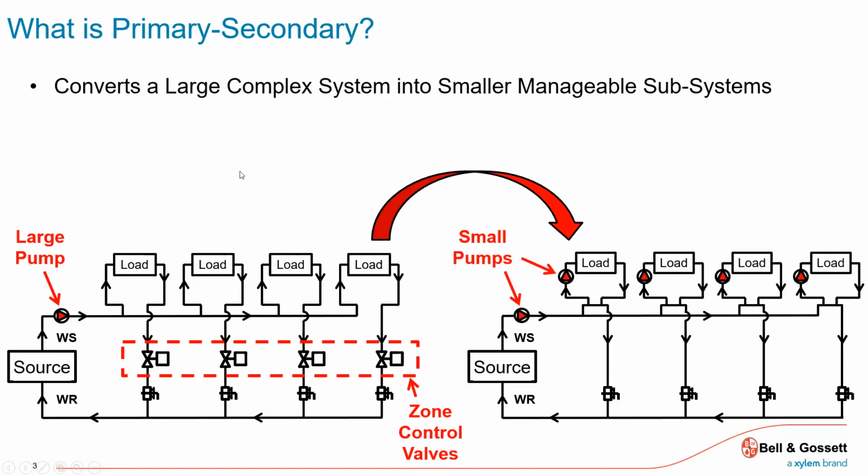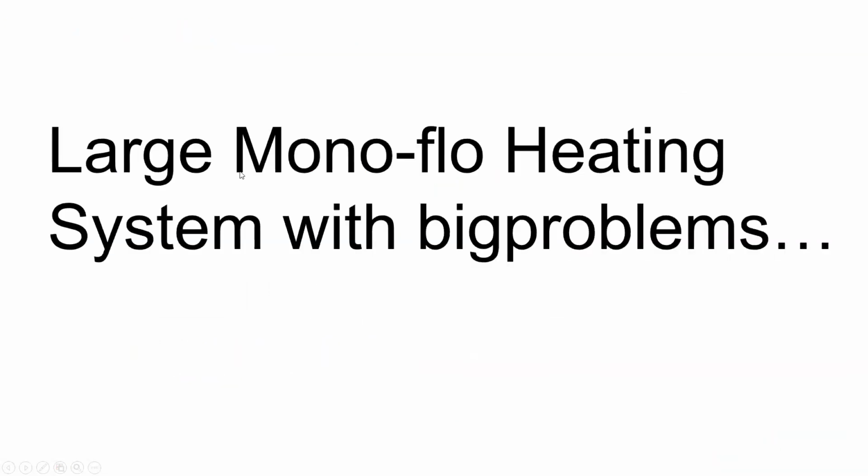And David, you had mentioned earlier the word decoupling. Sometimes they'll reference that right here, this little common pipe that's common to this loop and then common to what we'll call the secondary loop. And they're decoupling them by keeping those T's close together. I don't want to get in, there's too much to cover and not enough time. Let me see if I can do this. I want to jump ahead just a little bit and get to some of the rules of thumb, if you will.